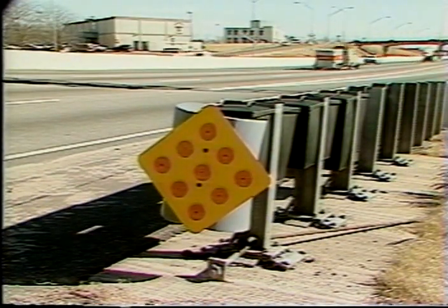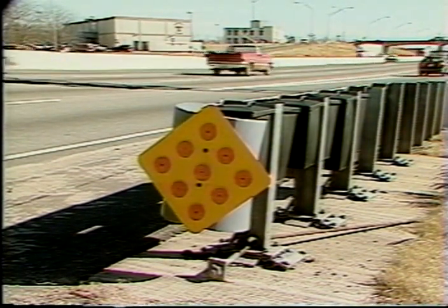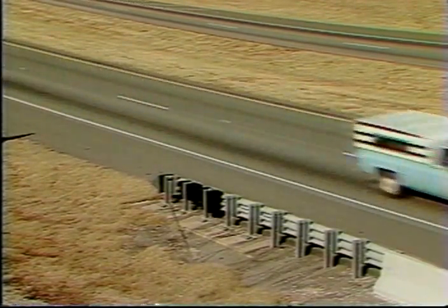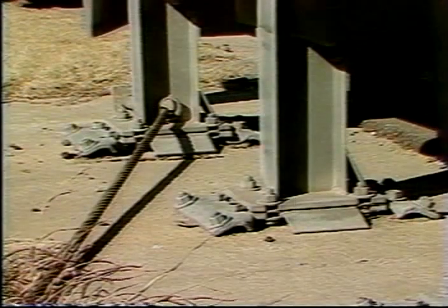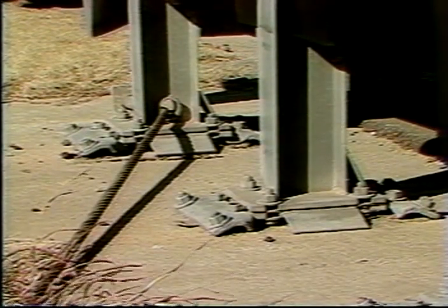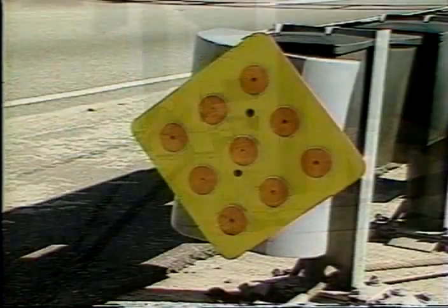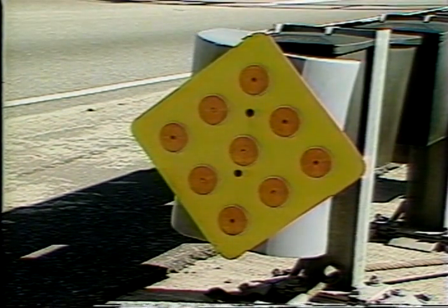A recent addition to the guardrail end treatment is the commercially available Sentry guardrail end treatment. This system combines features of other end treatments along with those of some crash cushion units. It has support posts with slip bases, collapsible Thri-beam fender panels, containers of sand on the first 3 posts, a cable terminal that assists in the slowing of the impacting vehicle while at the same time redirecting it, and a soft nose that collapses on impact, doing away with spearing dangers.